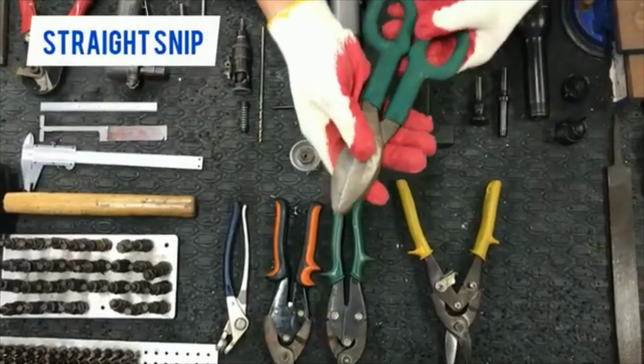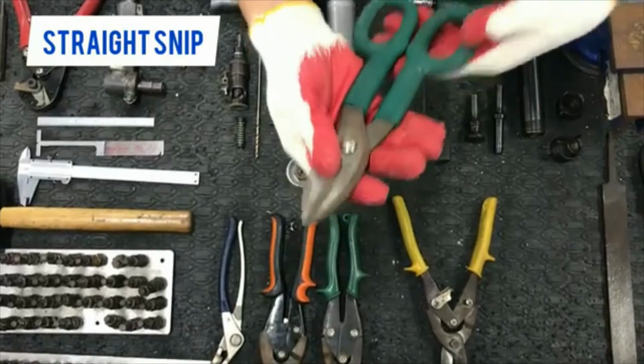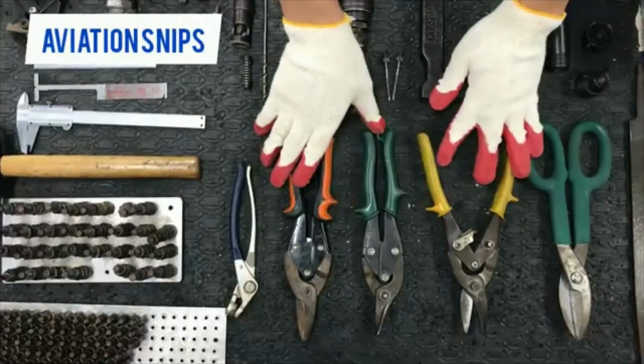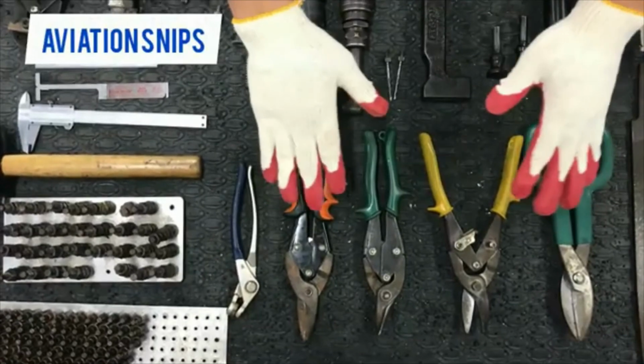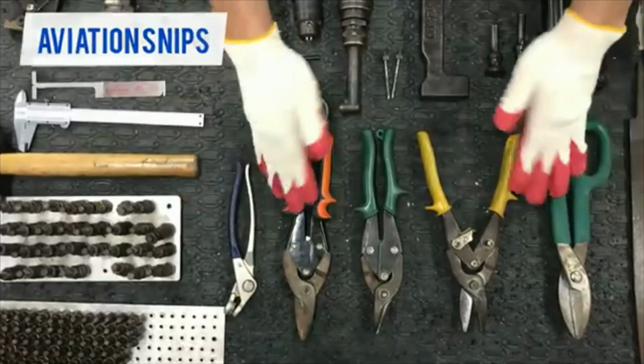Straight snips have straight blades with cutting edges sharpened at an 85-degree angle. Aviation snips are used to cut holes, curved parts, round patches, and doublers in sheet metal.